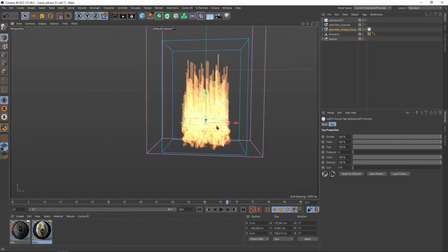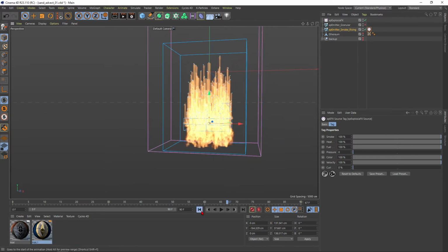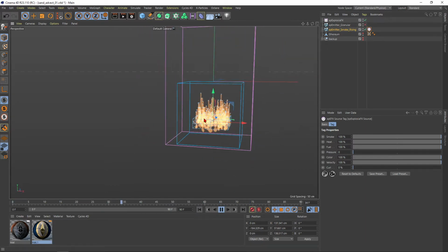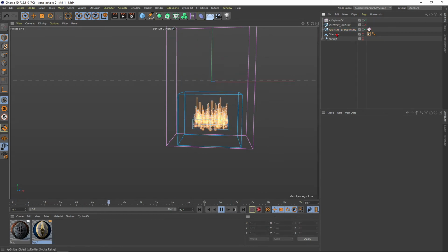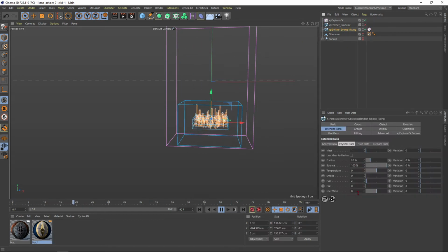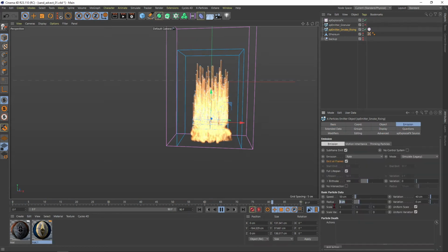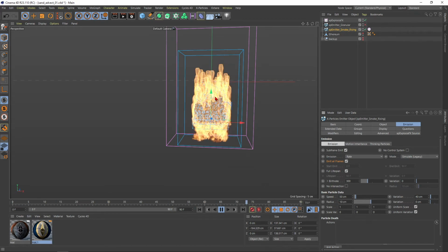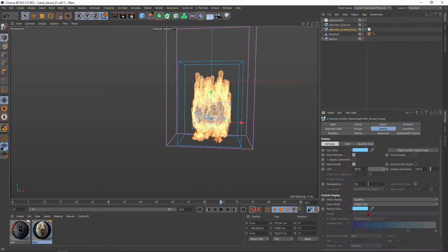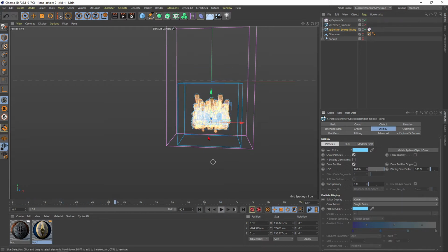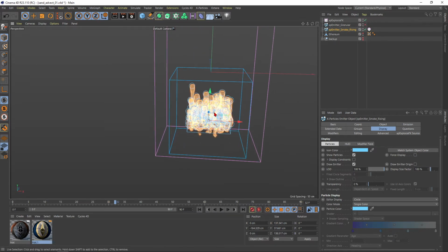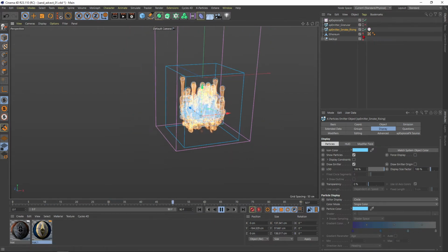All right. I'm a bit confused that the smoke is falling down here. Okay, that shouldn't happen. Interesting. So first, I guess the radius of these particles is way too small. So just go to your smoke rising emitter, go to the object, go to the emission and increase the radius. Put this one to 10. Alright, and you already can see the radius around these particles is way bigger. I guess it will help when we go to display, go to circle. Alright, and now you can see the radius of these particles, which will create the smoke or the fire. Okay, 10 seems to be a good value here, but I think we're not there.